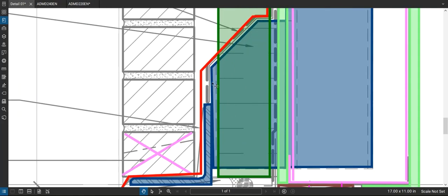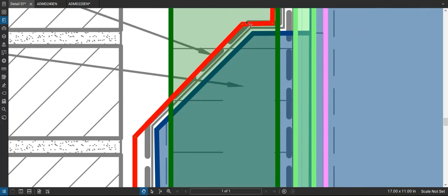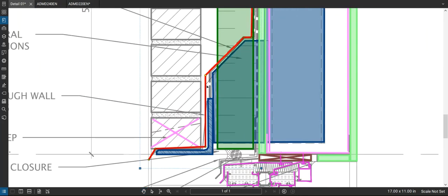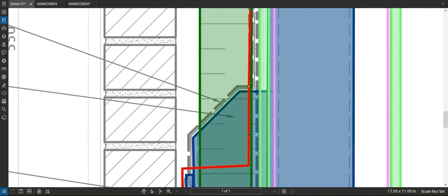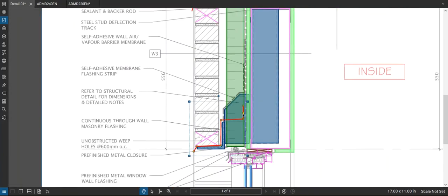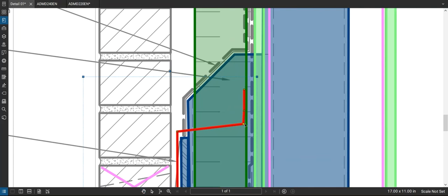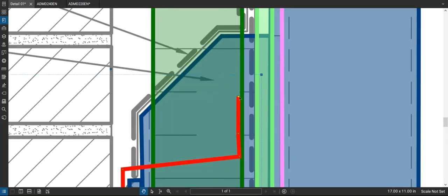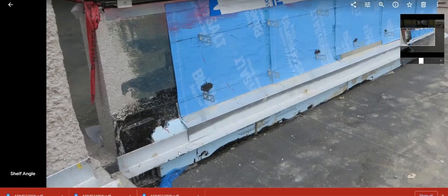In this case here, I believe they've angled this knife plate to provide a resting point for the flashing to sit across potentially there. Quite often though, this is done just like this right here, which I could actually show some pictures of in a second. You just want to get a slope on that, and then you cut the insulation on each side of that flashing. So I'll fix that up. But basically, there's that image right there.